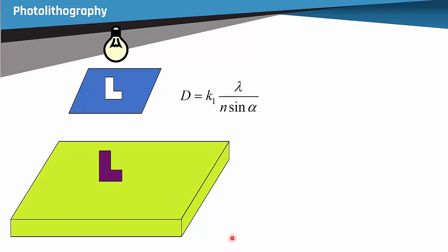The problem is that photolithography, and we'll be discussing this a lot next week actually, the critical dimension, the size of a feature that you can print, goes by this equation. Okay, so that's the minimum pitch, this d, and inside we have this lambda, which is the wavelength.